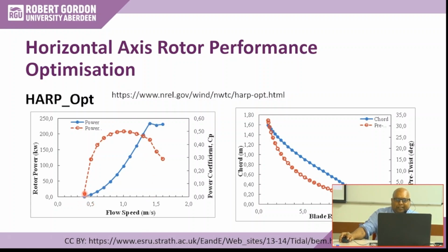And if you look at the power coefficient we talked about before, which is basically a substitute for efficiency, that value reaches up to 0.5 at a speed of 1, but it has a wide range. So this blade is very good. It has a wide range of power coefficient, wide range of velocity. You get a similar power coefficient of 0.4 to 0.5.